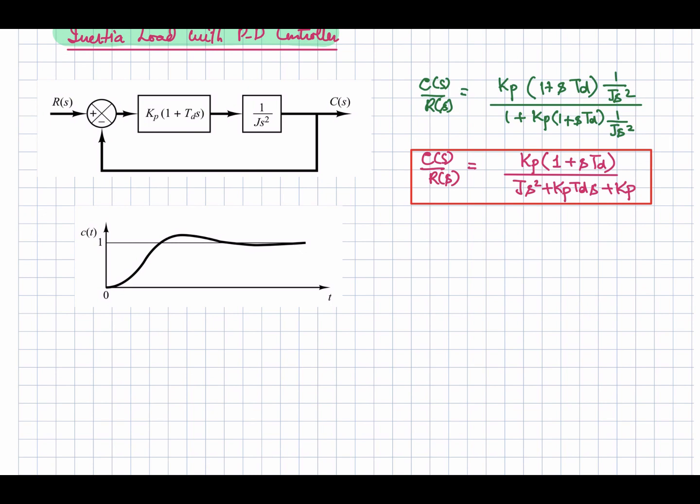Thus derivative control action anticipates the actuating error, initiates an early corrective action, and tends to increase the stability of your system. The derivative control does not affect the steady state error directly. It adds damping to the system and thus permits the use of larger values of the gain K, which will result in improvement in the steady state accuracy.